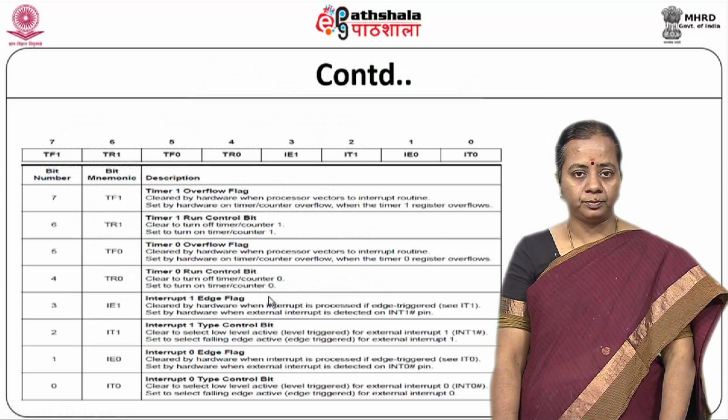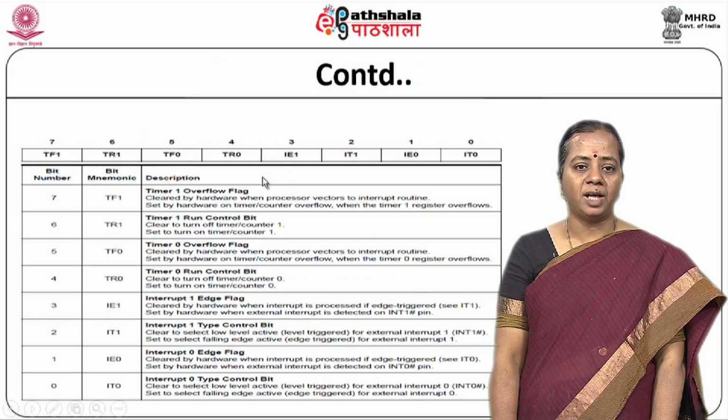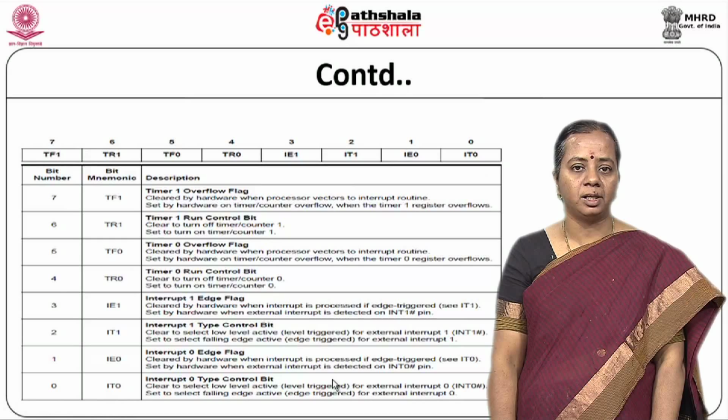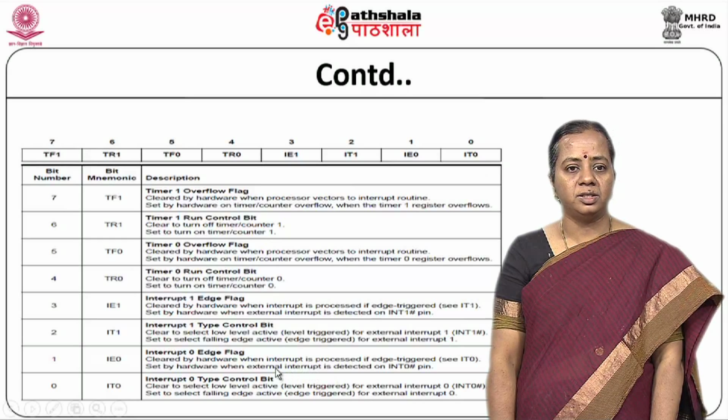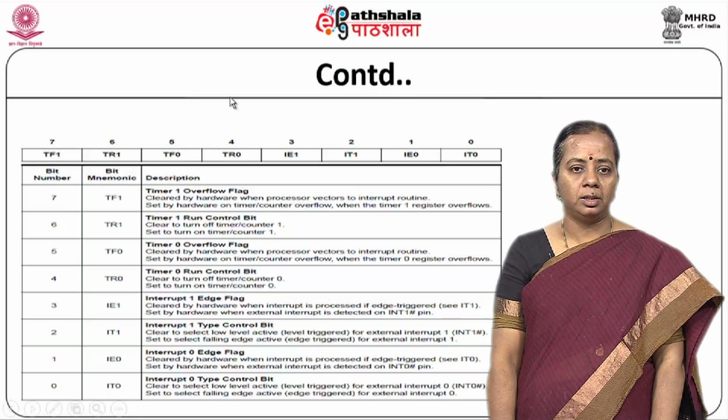So you see that along with IE, this TCON register also supports interrupt enabling and interrupt service. The TF1 and TF0 flags are available here, which invoke the timer interrupt.